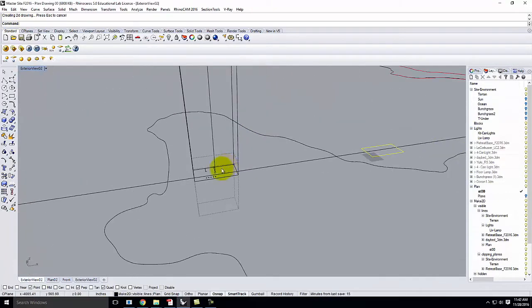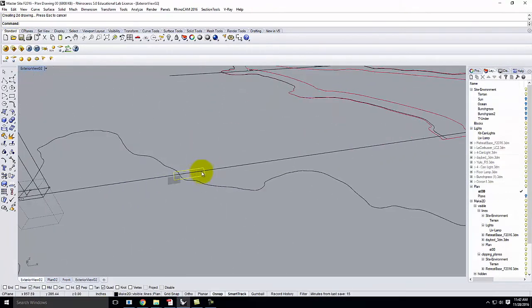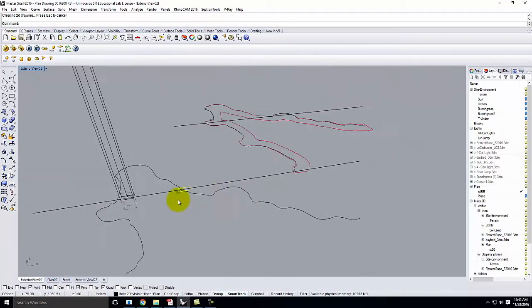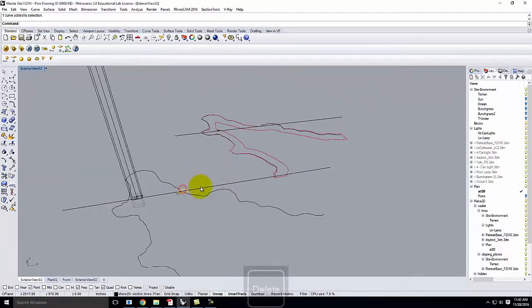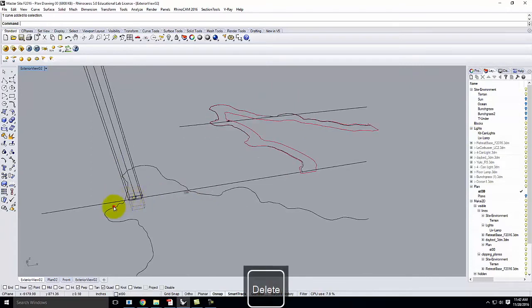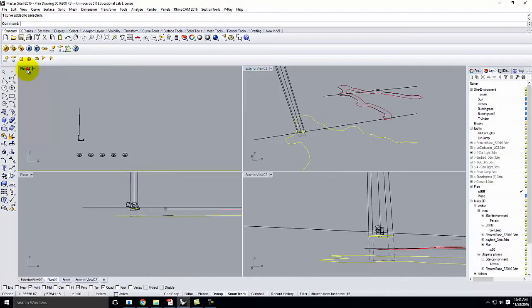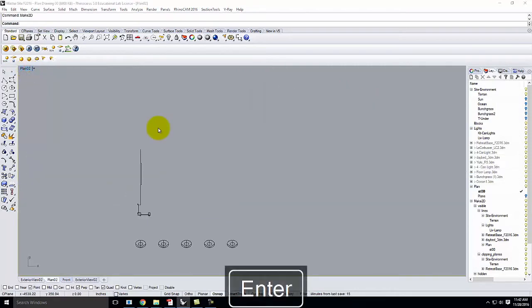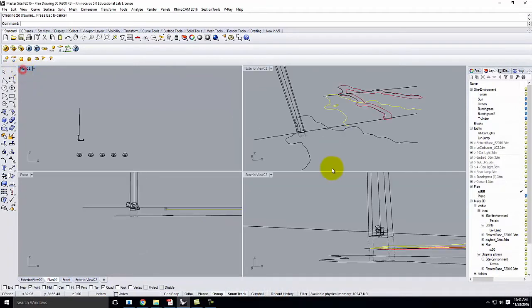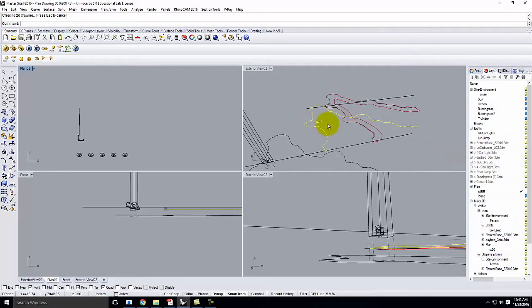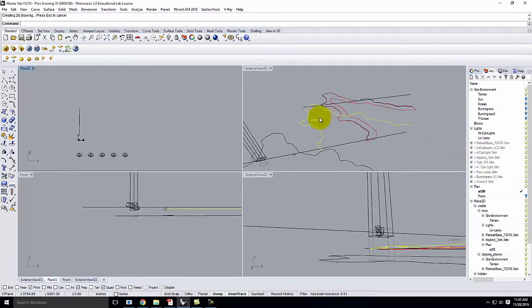We can go back to our exterior view, and it conveniently didn't line up the way it was supposed to. Hold on a second. Let me do a make 2D with this and this. Let's go back to exterior view here, make 2D. OK. And it now gave me the curve plus the rectangle. So now I can line up one on top of the other. So let me go ahead and move these.